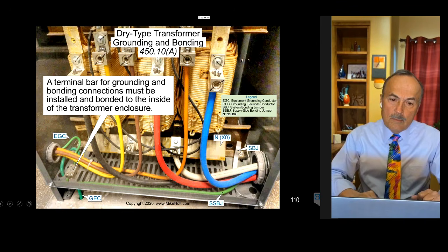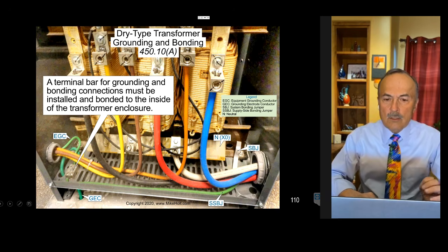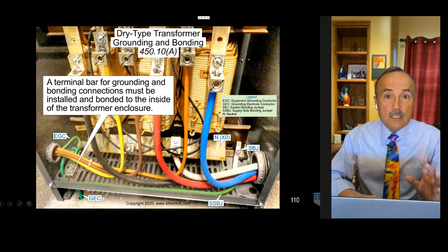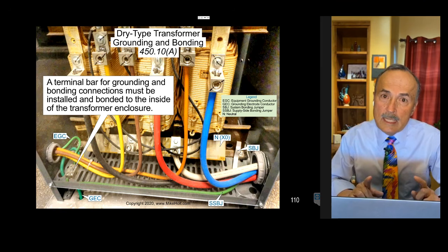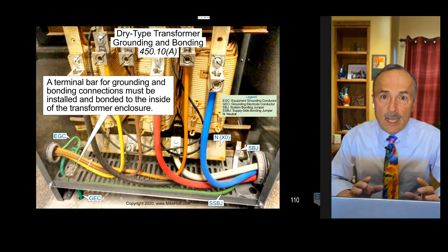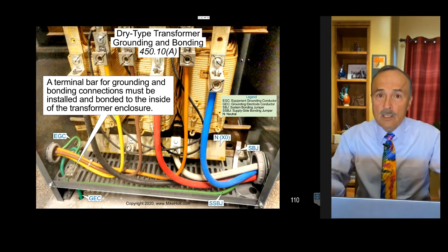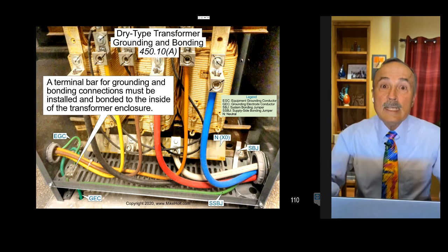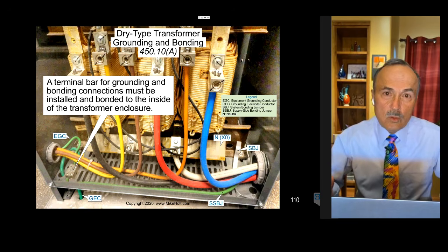By the way, you see these little identification marks, or signature marks. What this is supposed to represent is that this person complies with 110.14(D), which requires all terminals to be torqued according to the instructions supplied by the manufacturer. And by putting that little witness mark there, of course, you can just do that anyhow, because I don't have a torquing tool. Mike said, put those on there, and that gives the impression that we actually did torque. Nobody's asked me a question about details on torquing, so I'm not going to be getting into 110.14(D).